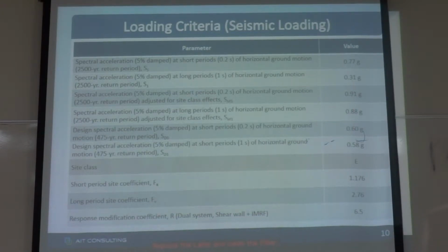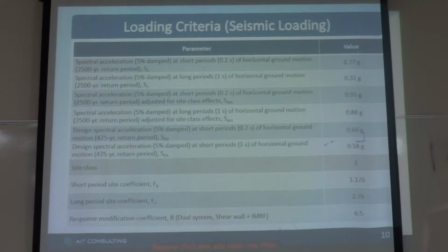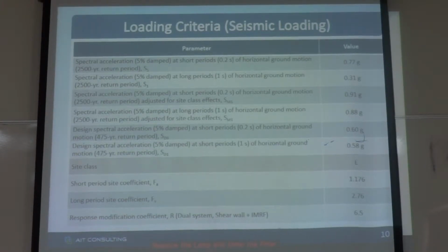Normally we estimate the natural period based on the number of stories of the building. For a 40-story building, it will be approximately 4 seconds. So you can see that we estimate only for a 10-story building. So if we design with this code for a 40-story building,